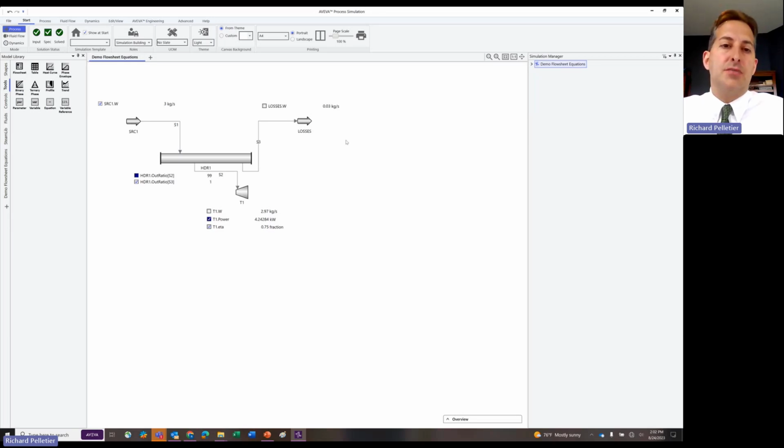In steam balances, this is very common to have a little bit of loss on your headers, and so you can represent that by having a stream coming off of the header, going to a sink, and seeing how much is sent in the losses, and usually you're trying to minimize this to a certain amount, right? So this is a pretty standard thing. Normally the headers are much larger with many more consumers, but I've simplified it for this example's sake.